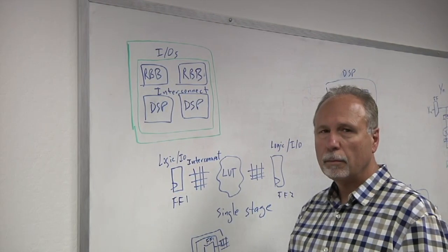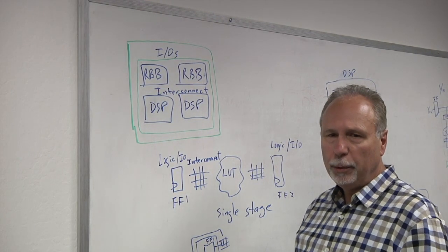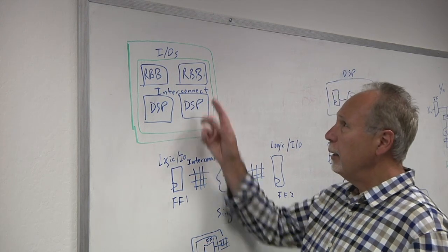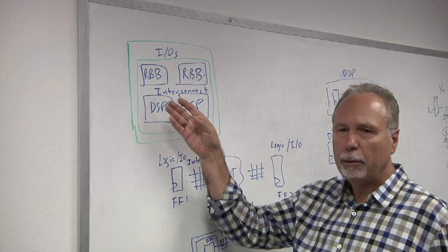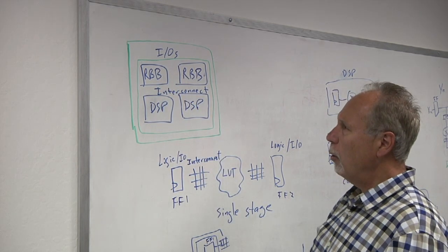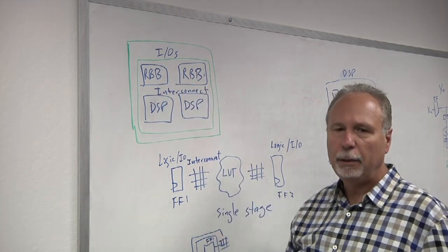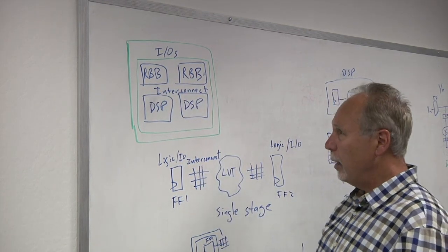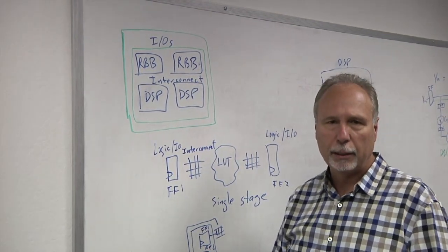Sure. So what are we looking at here? Some of the factors of embedded FPGA that contribute to the performance are the IOs, how fast the IOs are, how fast the reconfigurable building blocks or CLBs are, and also the interconnect fabric, how fast can I connect the logic blocks, as well as some of the fixed functions like DSPs, how fast do they clock.